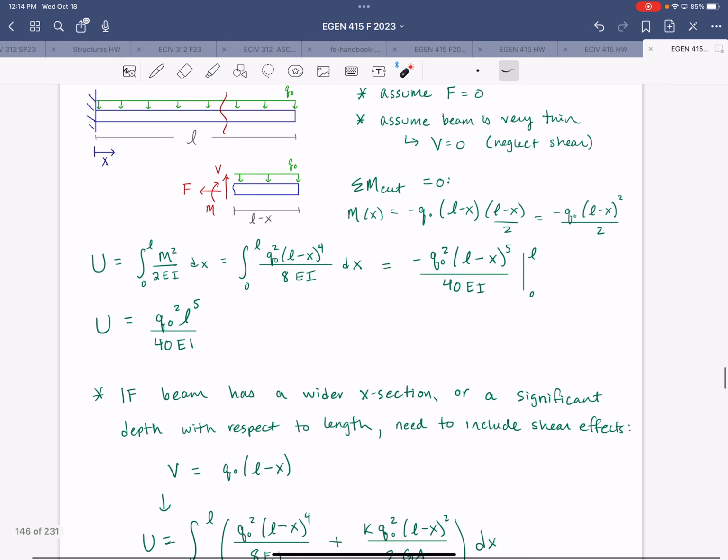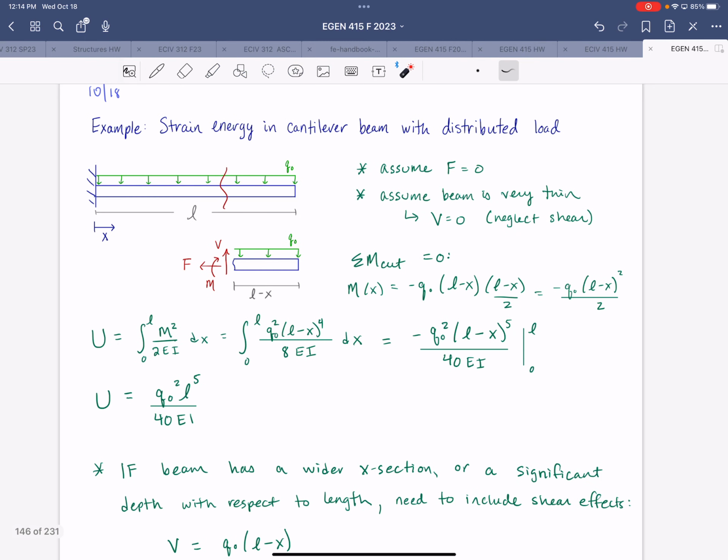So for a simple cantilever beam, the longer that beam is, the less significant shear becomes. But in a short, squat 2-story building, it's not leaning like a cantilever. It's just shearing, basically. Exactly. You have a lot of shear behavior going on there.